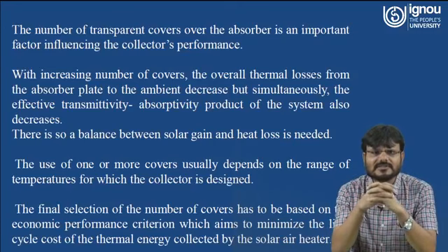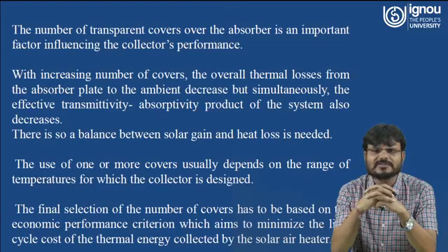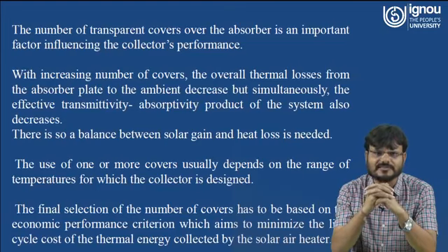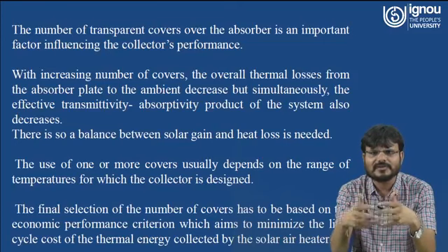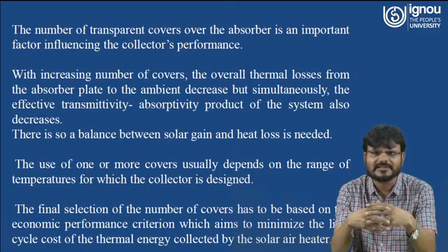Here you can notice the number of transparent covers over the absorber is an important factor influencing the collector performance. With increasing number of covers, the overall thermal losses from the absorber plate to ambient decrease. But simultaneously what happens? The effective transmittivity and absorptivity product of the system also decreases. So what do you have to do?